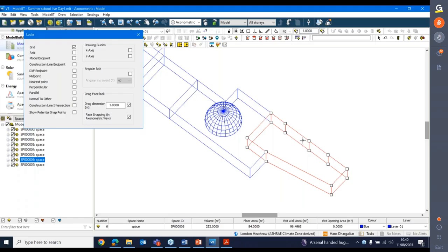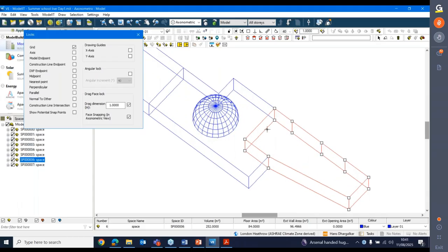Okay, but you can't delete a surface. In that internal partition, I could draw, because you can draw windows or doors in any surface of the building that you wish. You can also draw holes, but you can't draw a hole in an external surface. So again, that's another top tip. If you try and draw a hole in an external surface, you won't be able to run your thermal simulation. It's an error. Okay, so don't do that. But you can draw holes in internal partitions or internal ceilings.